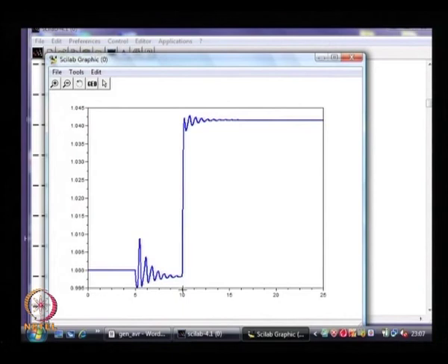Of course, if I give a step change in the automatic voltage regulator at 10 seconds, of course, it was 10 not 15 seconds, at 10 seconds, the terminal voltage of the machine goes up. So, it regulates it, okay. It changes the value according to the set point. Okay. So, it has gone to around 1.045, roughly. So, this is how the AVR behaves.